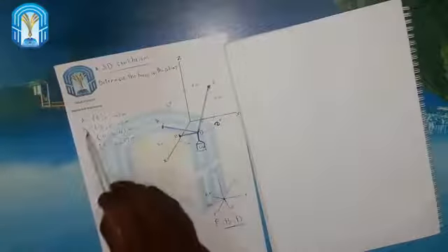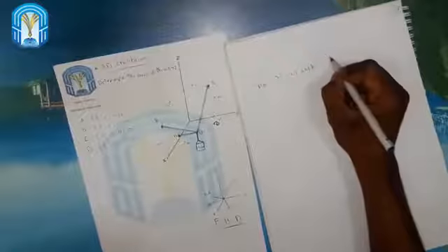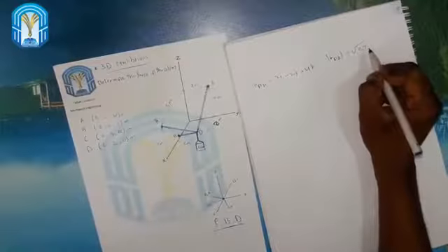We have these positions in meters for A, B, and C, and D. Now we'll find the position vector RDA equals 3i minus 2j plus 4k, and the magnitude for this, DA, is the square root of 3 squared plus 2 squared plus 4 squared, which equals the square root of 29, and equals 5.4.